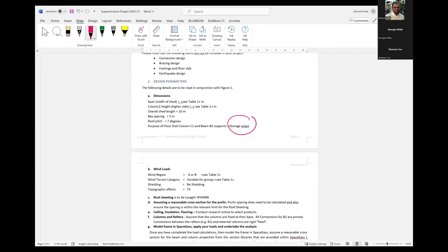For example, if we return back to our example here, how much is the storey height? You need to find the height of this area, which is 5 meters. So the live load on this one will be 5 times 2.4 kPa, so the value will be 12 kPa. I just try to choose 5 because 5 is simply